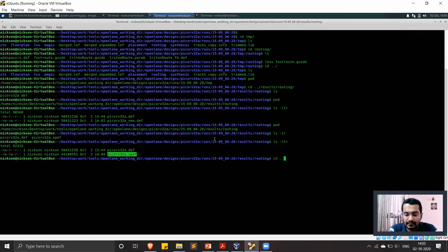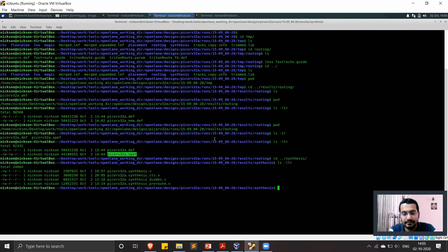What I mean is, if you remember, we had got a new netlist post CTS, and pre-routing actually this antenna diode insertion happens. That means you are inserting a component into your design, so the netlist will be modified.